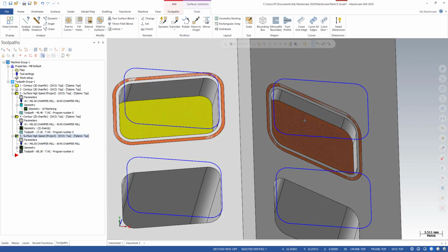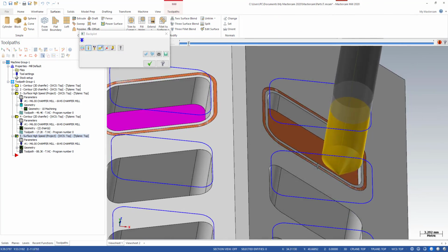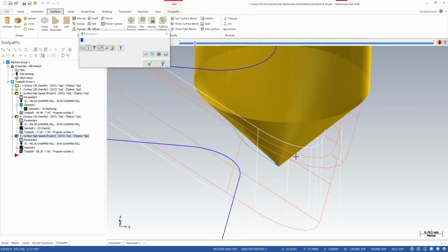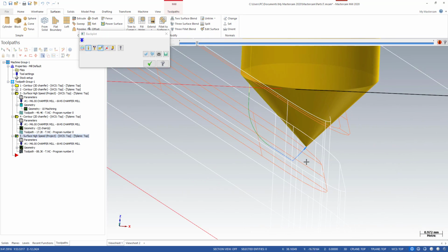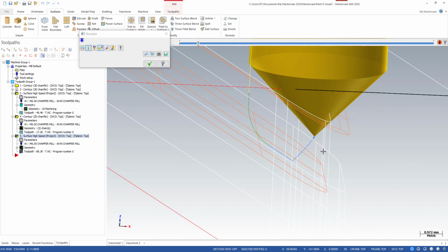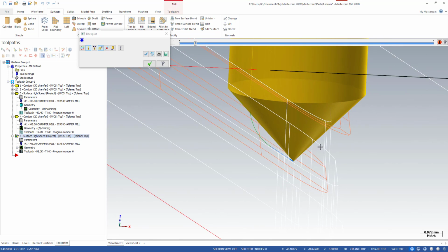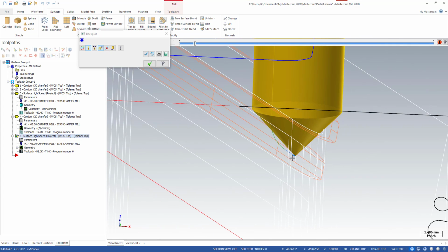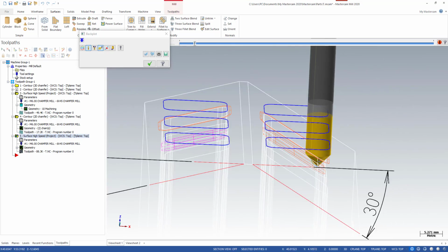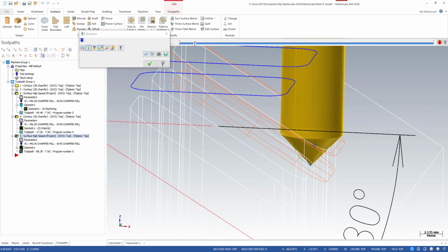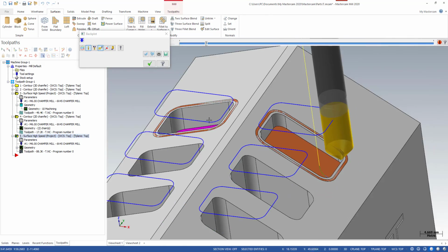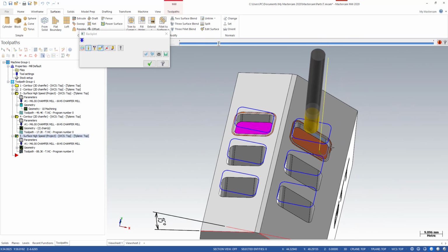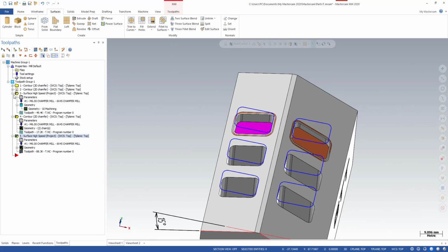If we select this and this, you can see this toolpath. The tip can find somewhere to do the projection. Yeah, you can see before it hit the chamfer, it hit the edge of the chamfer. It follows this surface. So that's why I create this surface and this surface, just for a complete toolpath, not interrupted, right? Okay, I hope this makes sense, right?